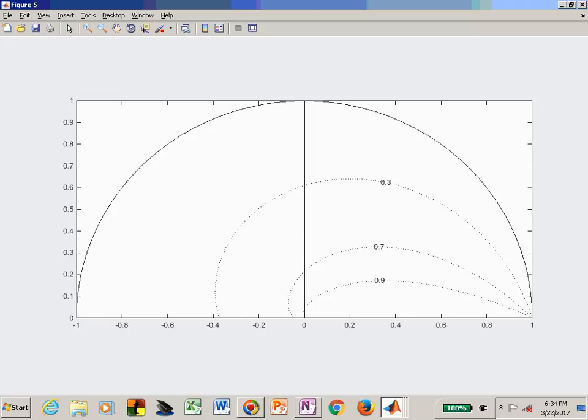So now you have tools, and maybe I can post some of these z-grid things on the website for you to use if you're now trying to sketch or plot different z-plane pole locations that might have particular zeta values. Or you would just say, oh, a 0.6, you might have to get out your ruler and find 0.6 here and then measure that off and intersect that with your logarithmic spirals.